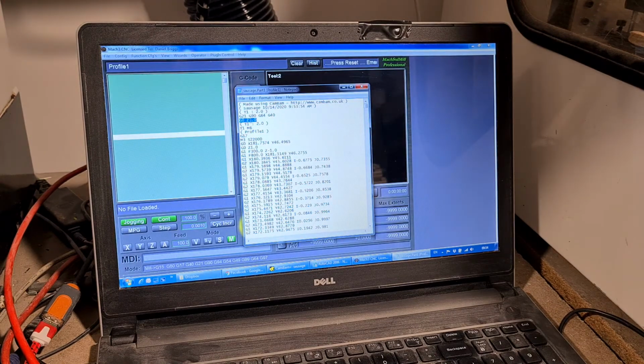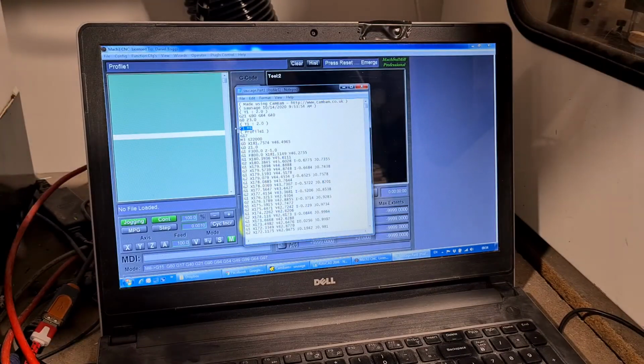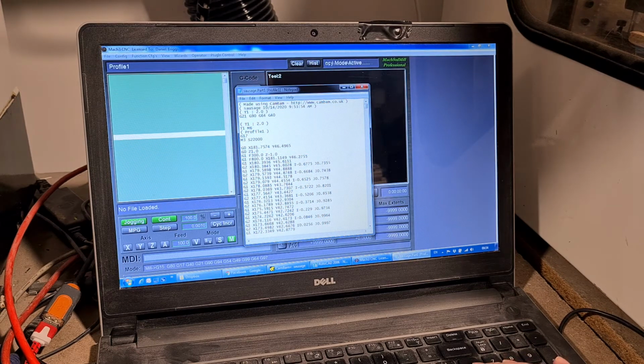So what will happen here is your tool will go down to 3 millimeters when it does a tool change. So it'll go down and then come back up to do a tool change, which is completely pointless. So take out that. I like to put it under the once the spindle started and paste it there.